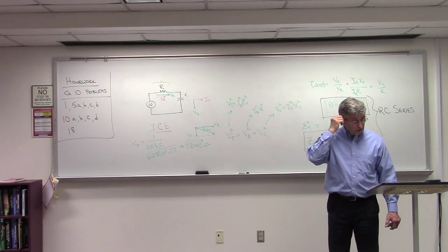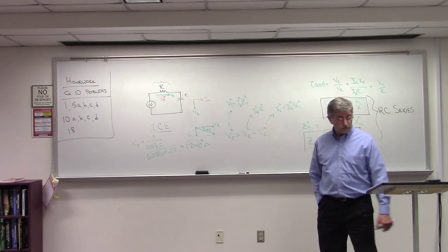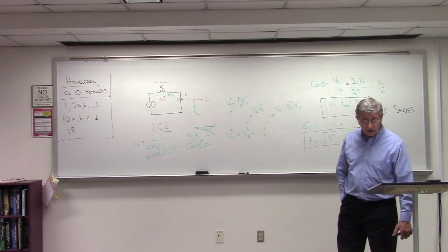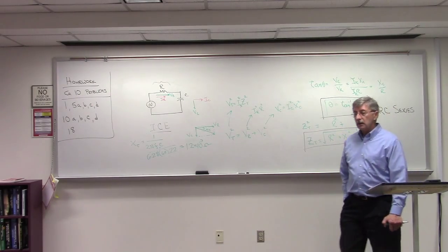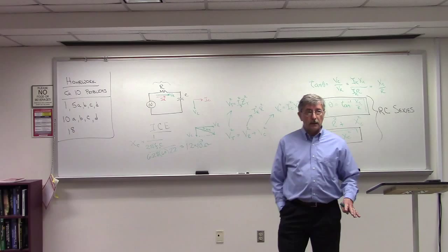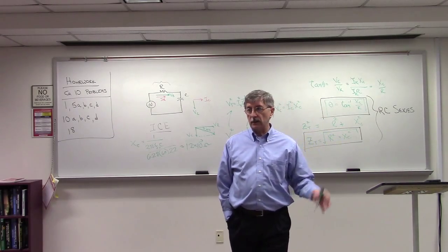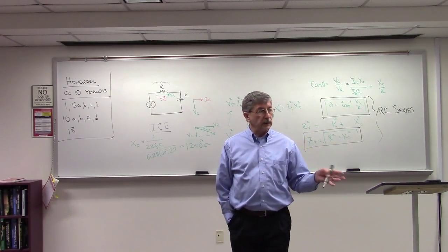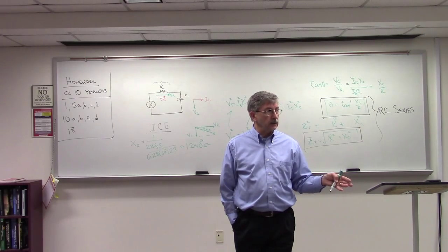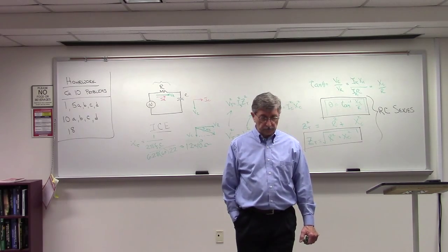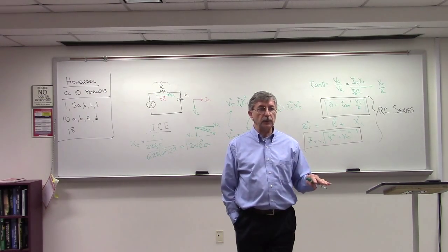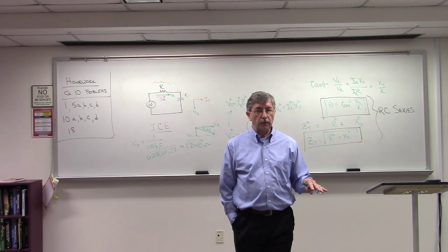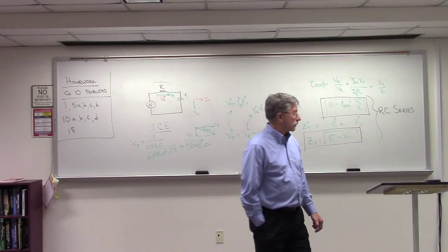So you're going to have an impedance of approximately 1K, and the resistor is going to dominate so much that there's really not going to be any phase shift between voltage and current. Well, Jared, what'd you get, like 10 to the minus something degrees? It's crazy. So that's an example of where you have a resistor that just dominates the entire circuit.